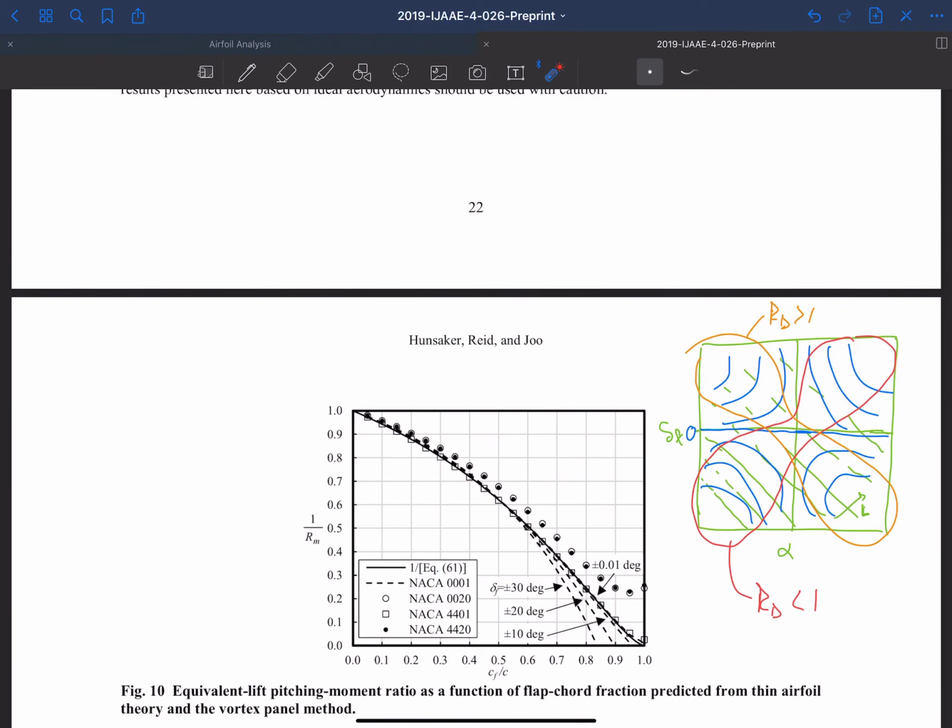We usually do not try to, at some lift coefficient, drop it by lowering our flap deflection to get down to a lower lift coefficient. But usually we're going to do a combination of flap deflection and angle of attack and follow a trajectory that goes more in this direction. So these contours, by the way, got down to about 80% in the extremes, and then closer in here, it's 95, 98, and then cross one, 98, 95, and then you can get down to lower numbers here.